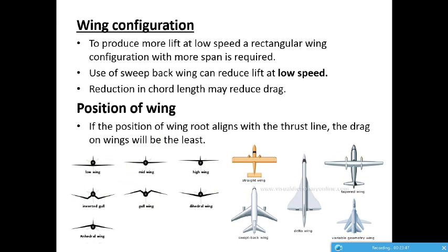The first one, this low wing aircraft, is usually used for racer aircraft, which has less stability and more controllability. And this is a mid-wing aircraft, usually used for sport flying, such as inverted flying. The high wing aircraft is usually meant for providing the highest amount of stability.